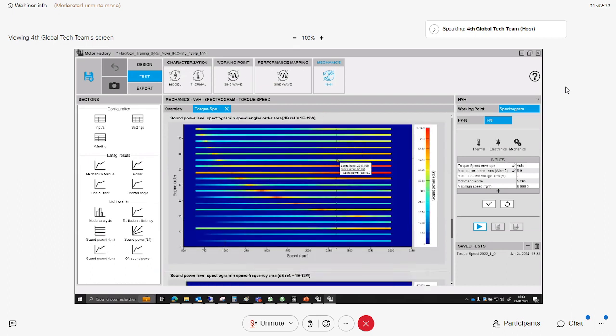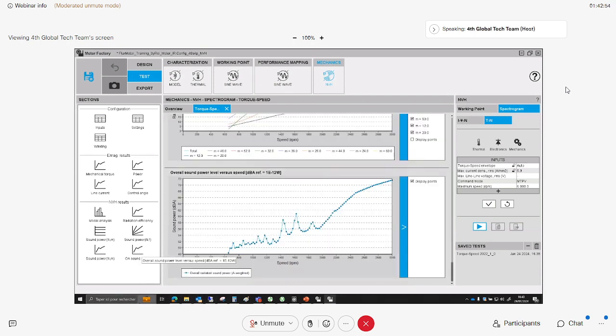And then this is something where we mix analytical computation and magnetic pressure computed from flux study in transient magnetic application. Yep. What I need to have a look at, as a designer, is really where the machine is noisy. I can say that we can have here some resonances.